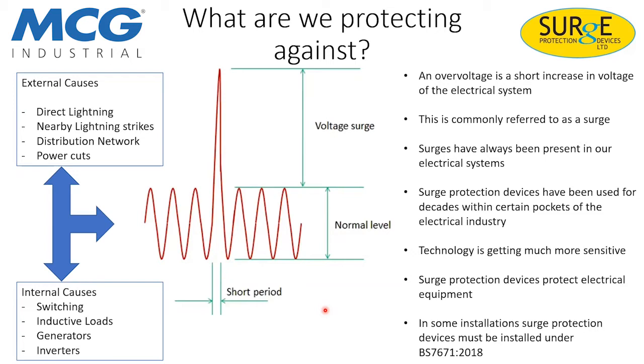We also have surges that come from inside of our property, and this is something that most people aren't really aware of, but actually up to 80% of surges can occur inside the electrical installation. So we have things like switching surges, which literally are as simple as they sound. Every time you flip a switch and pull a load, you create a surge in the system in varying degrees. We can have inductive loads, generators, inverters, air conditioning units, lifts, all these sort of big pieces of machinery, as well as our tiny little pieces of machinery that we use in our homes, like the DC drivers in your washing machine, all create surges in the system.